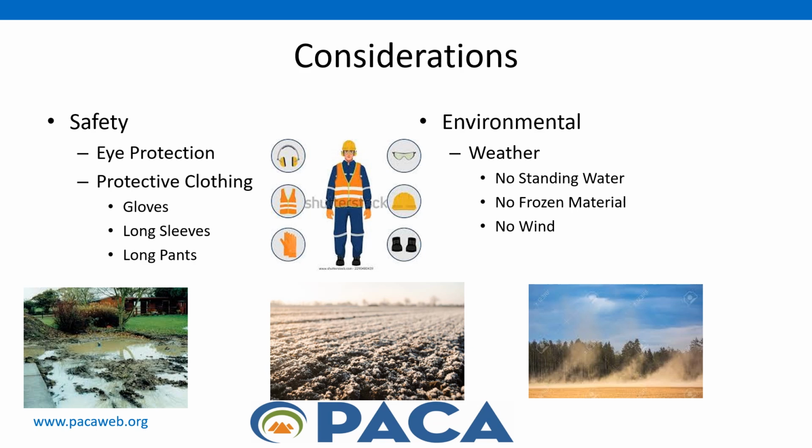The cement could be lost and the blowing cement may cause a dust nuisance to the general public. When handling cement, always wear proper protective gear, including eye protection and protective clothing, which would include gloves, long sleeve shirts, and long pants. Cement is a caustic material and protection is necessary.